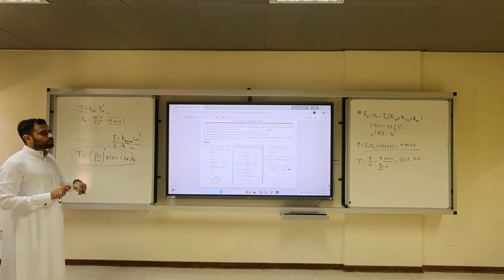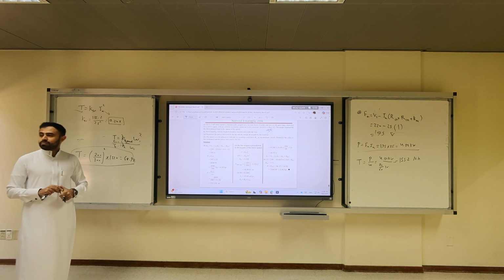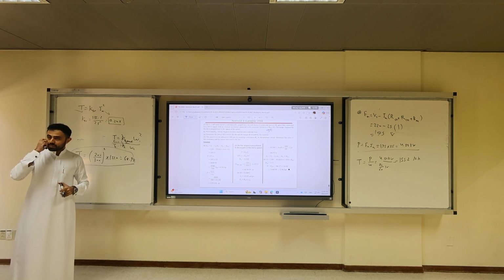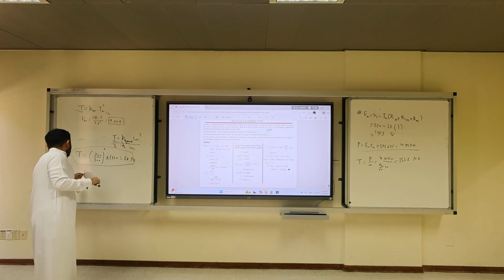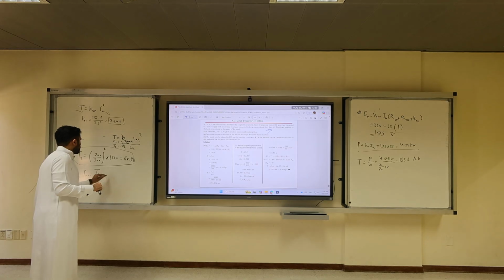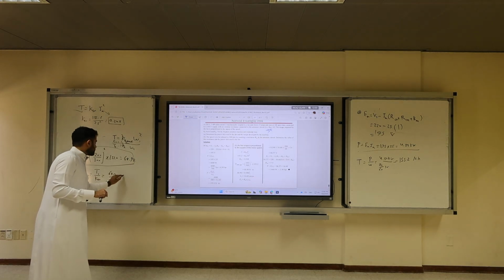And then what will happen? You're going to have a new IA because you have a new, different torque. So what is IA2, the new IA? You're going to use T2 over KSR, which is 68.98 divided by 0.248. You're going to get 16.68.